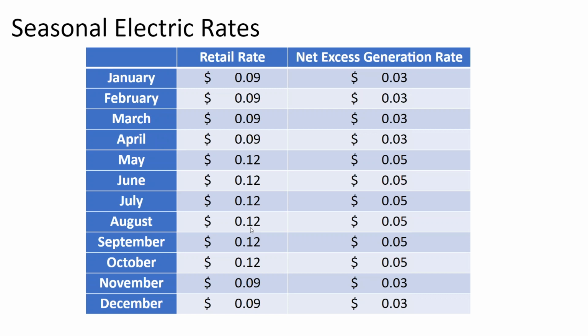And in fact, it gets more nuanced when you get into off-grid residential, because instantaneous electric loads of homes can be 30 to 40 kilowatts and still be well within the limits of a 200 amp service panel. So you have a lot more you have to learn that's site specific. At that point, you have to go and find a NABCEP installer in your area who has more experience with your local market in terms of electric use and homes. Not that I can size it up for you, but you'd have to know a little bit more about what's inside the home.